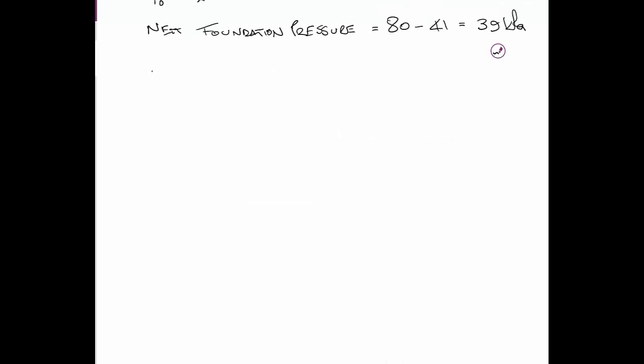Alright, so we're going to work in the undrained condition. That's short-term total stress, and that's going to give us the initial settlement. As soon as we load this thing up, this is the settlement that it's going to undergo. They've already calculated the stress dissipation with depth: the change in sigma 1, or change in sigma v, at the midpoint of this layer equals 0.7 by 39, which was the net pressure, which equals 27.3 kilopascals.